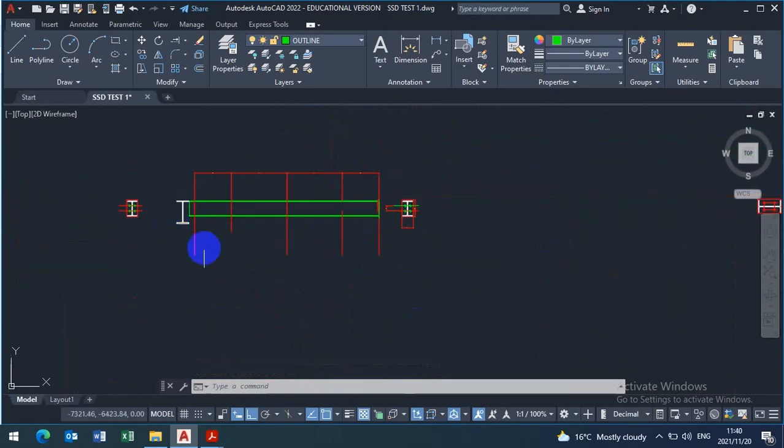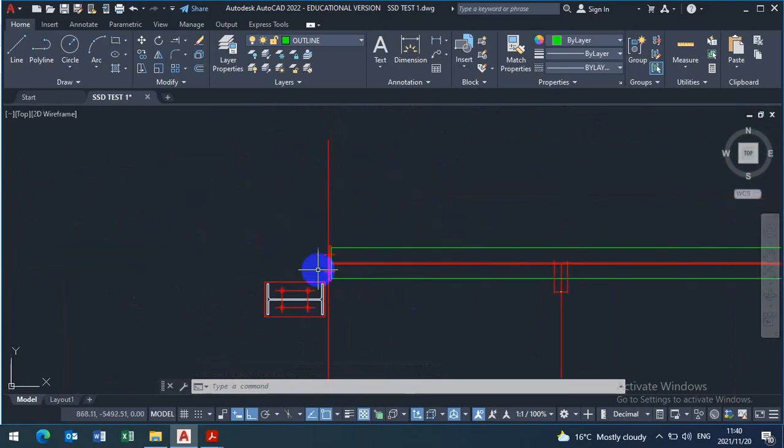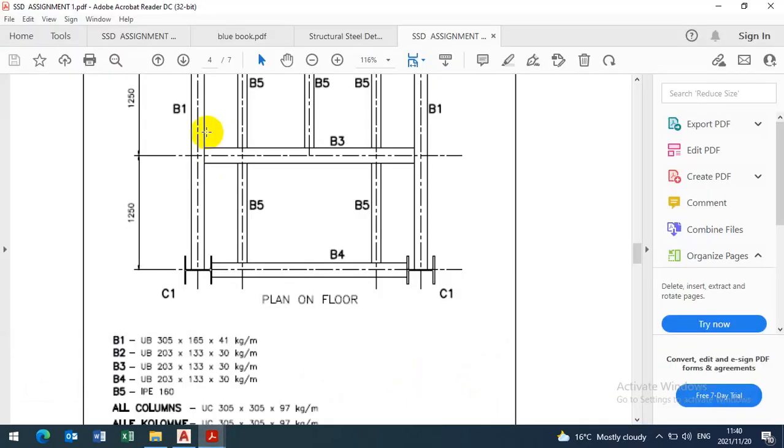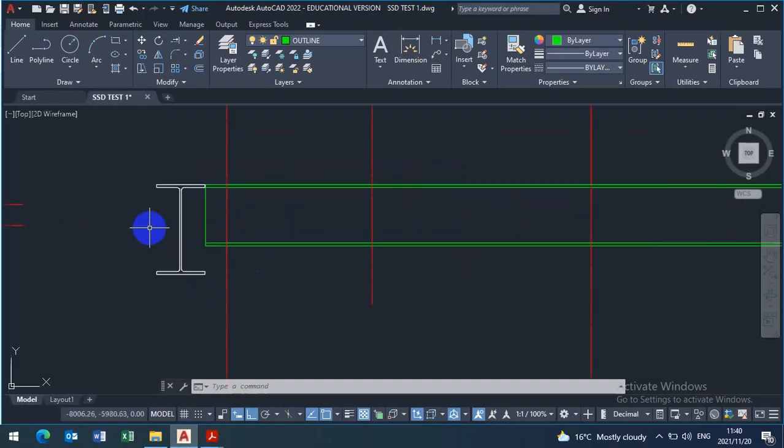Okay. The beam 1 was ending with the columns here. That was on the column. But when we look at beam 3, I've already mentioned that it's touching here on the web. So you need to have a notch, but the notch you can't show on the top view. If we are looking from this other side of the beam, you will see the plate here, and the plate here, and the plate here with the holes. In fact, we'll just show the holes on the flange. Okay. All right, so now notching of this beam.